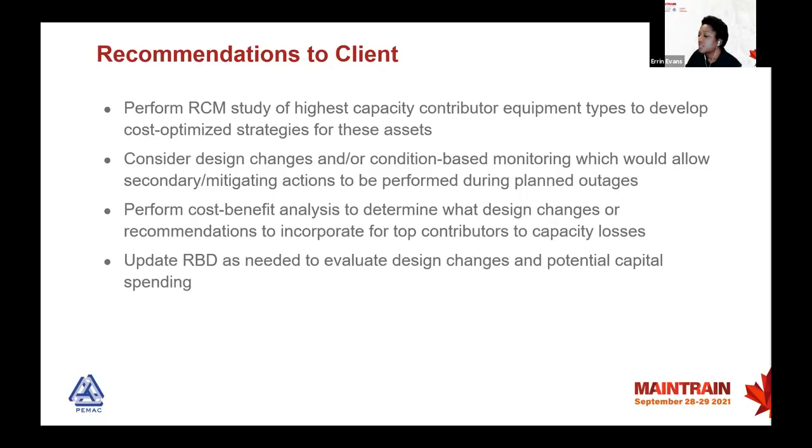The recommendations to the client were to perform an RCM study of the highest capacity contributor equipment types to develop cost-optimized strategies for these assets, and consider design changes and/or condition-based monitoring, which would allow secondary or mitigating actions to be performed during planned outages. They should also perform a cost-benefit analysis to determine what design changes or recommendations to incorporate for those top contributors.